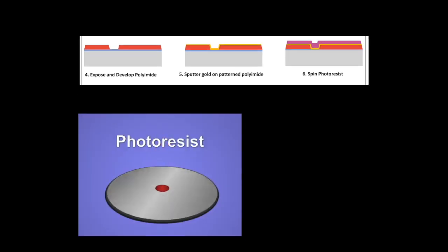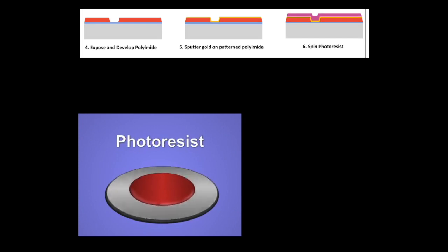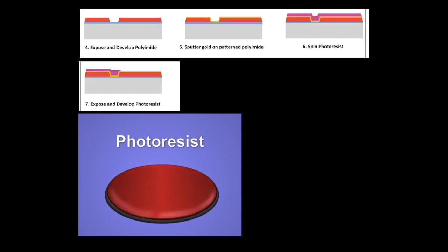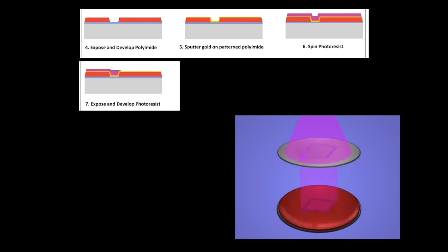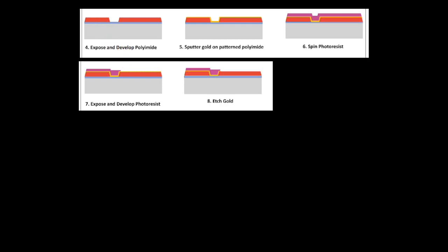Photoresist solution is spun onto the disc while being softly baked to evaporate the solvent, and then is exposed to light in a masked template, which can then be developed chemically so that the template design is remaining on the disc and the rest of it washes away. In this case, the negative space of the photoresist layer, the part of the photoresist which was not cured, washes away. And that space is actually exposed gold.